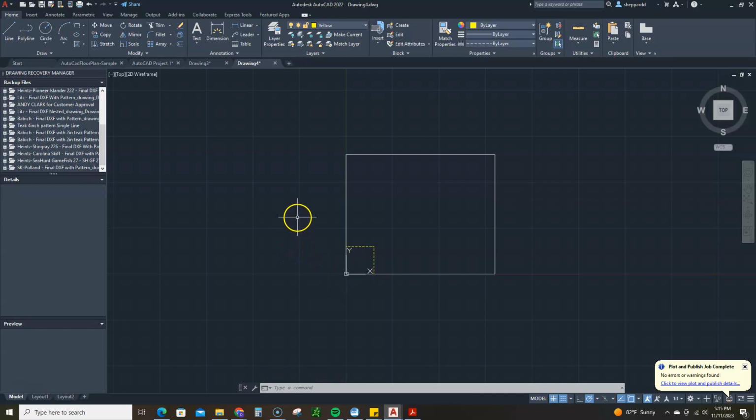One of the things that I always like to do is go ahead and draw a midpoint. And I can always get rid of this midpoint later. But this always allows me to take 2 lines like this and mirror those lines. I can mirror that one, and I'm going to do the same thing with these 2. There we go. Forgot to hit no. Alright, so I have that part.